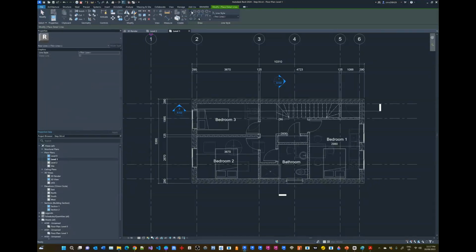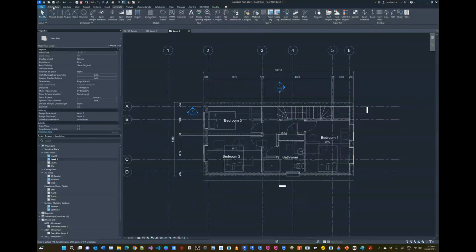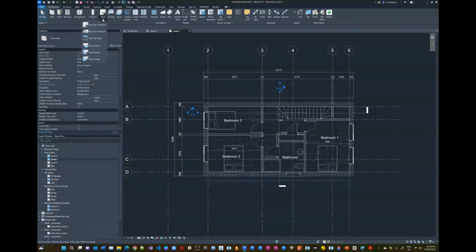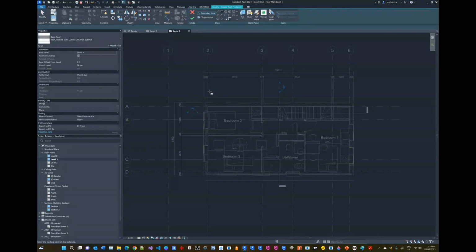So I'm going to do the same here using detail lines. I'm going to offset 350 millimeters from those walls, and I'm going to create my roof footprint directly on that, and I'll cut it flush here on these walls on the east and west ends, just because we can. So I'm going to go to architecture. From here, I'm going to choose roof by footprint, just like we did in the first test drive exercise. And I'm going to use the rectangle tool to just draw this in quite quickly.